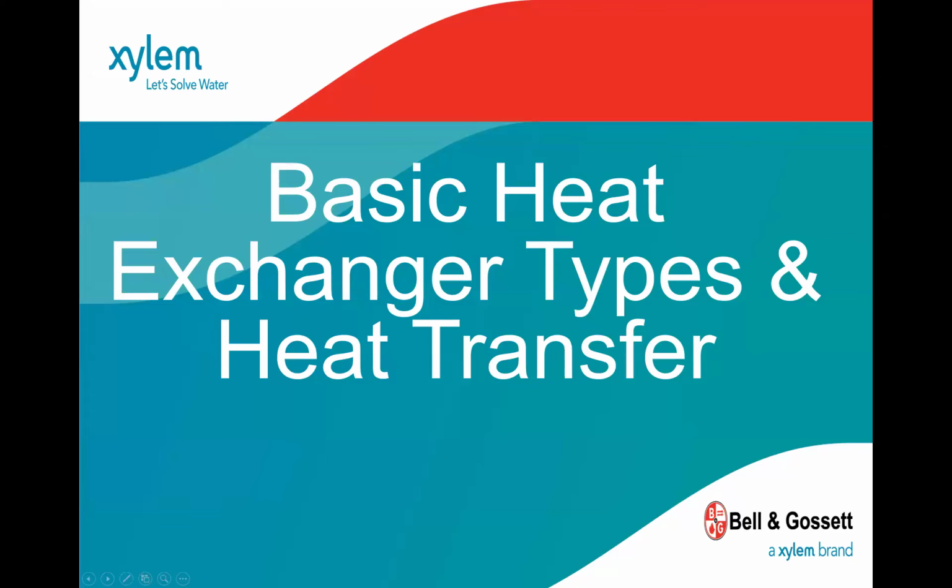So like a brazed plate unit, you may be able to get it with a copper nickel or a nickel braze if you need something to be more resilient for maybe a pool application, versus if you have a plate and frame, you have a few more options where you'd say, okay, instead of one or two options, I want to do titanium and I want to have these type of gaskets and this type of connection. But as you can imagine, when something can be assembled, it would make sense that it would be easier to configure. So those are the two plate type heat exchangers. The bottom is the brazed plate, then the plate and frame up top.